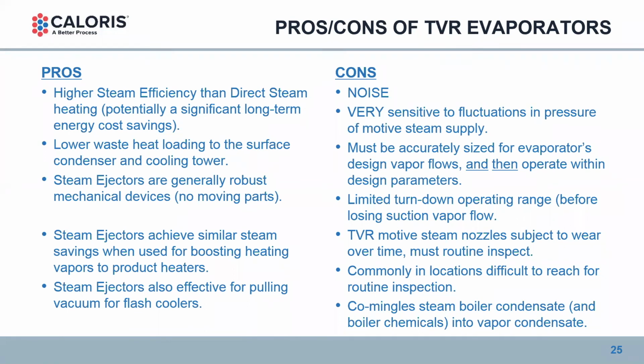I said they are robust, but they are subject to wear. Periodically, the steam nozzles, with water droplets of saturated steam going through them, will over time get etched away, and they do periodically need to be replaced. Not every year, maybe every decade, but it all depends on the quality of your steam.